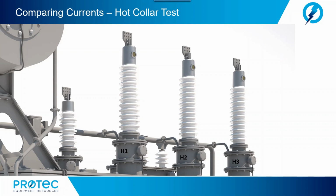In order to measure only the power factor of the bushing, we put a circular ring which acts as a conductor around the bushing, a hot collar, which we connect to one side of the tester and the other side to the top of the bushing. In this manner, we can measure the power factor, capacitance, and leakage current of only the bushing.